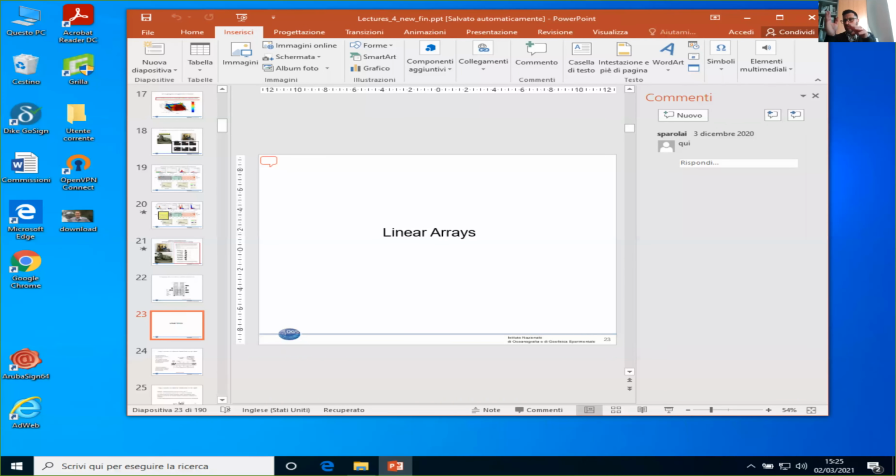So it was good to also have small vibration measurements which could fix the parameters better, at least for the numerical simulation, and then for strong motion, and get probably a more realistic estimation of the dynamic behavior of the building. I don't know if Chiara is here and she's working a bit on this, agree with me, but that's mainly my experience.